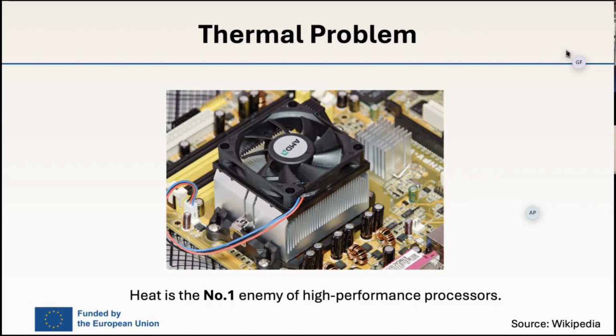And if you are doing high performance computation, whether it's in mobile, desktop, or cloud, heat is your number one problem, because if you do not dissipate the heat, your chip will get damaged, and it has severe reliability consequences for your chip. So heat has to be taken away. In embedded form factor, that heat is especially difficult to take away, because we can't really put a fan on your mobile devices and so on because of the given form factor. The problem is that the 3D design makes this worse.